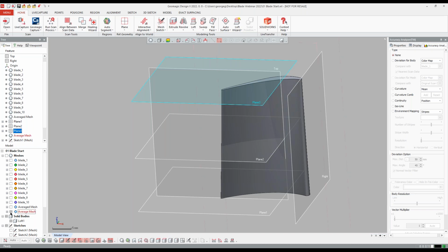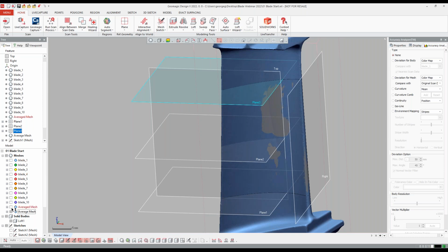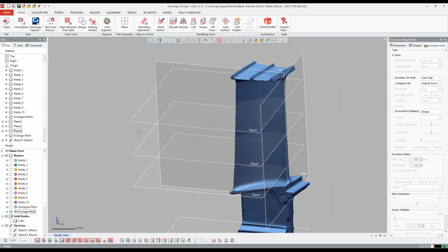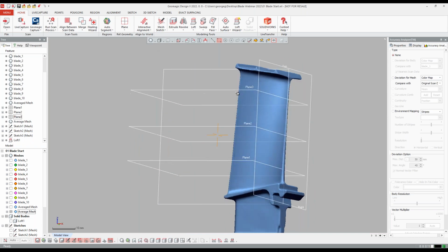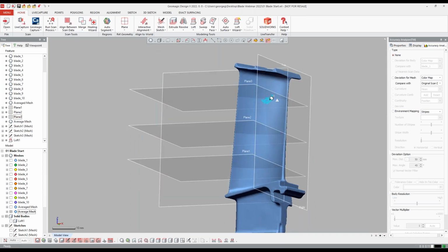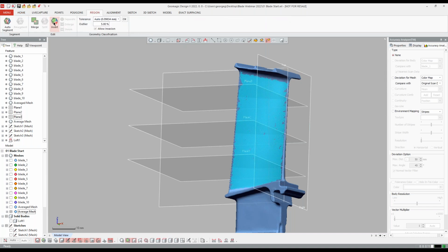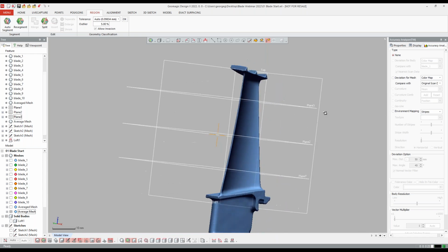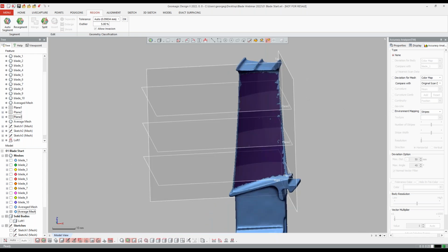We also have the ability to create a loft using a surface loft. So if I just go ahead and turn this off and I come over, I can actually select a bunch of geometry here on the surface of that part. I can come in and I can create a region out of it. So I just selected that geometry and I created a selectable region.